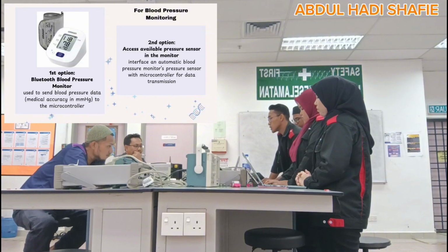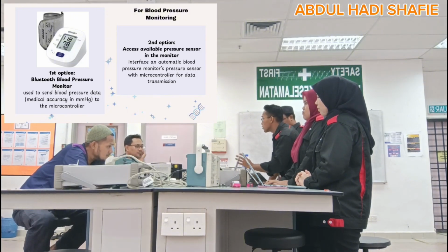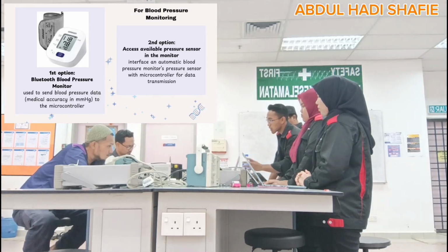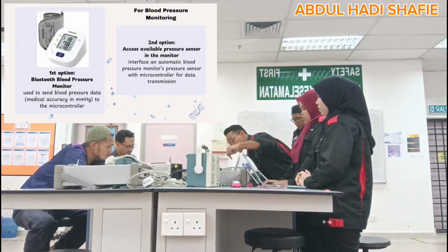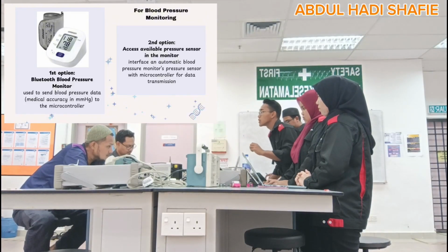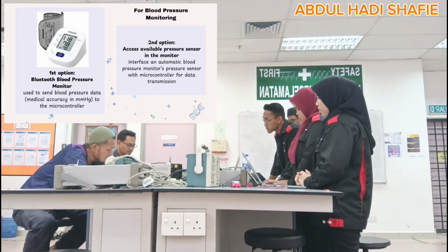We use the cuff also, but we design the motor and also the valve to supply the air pressure. From the cuff, we don't connect to the monitor, but we connect into a pressure sensor that will be integrated into our motherboard.